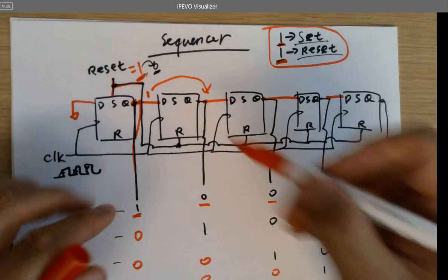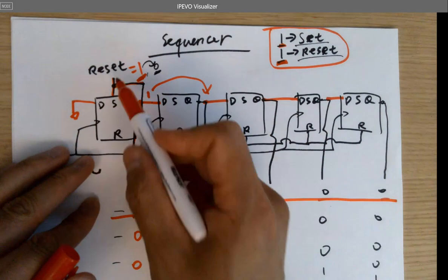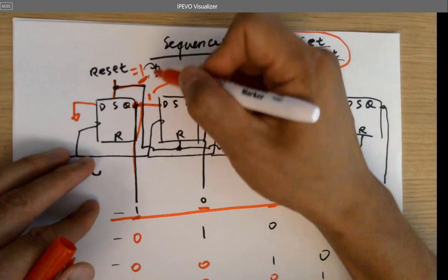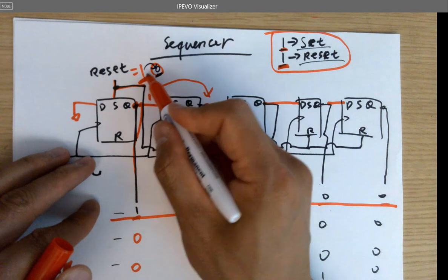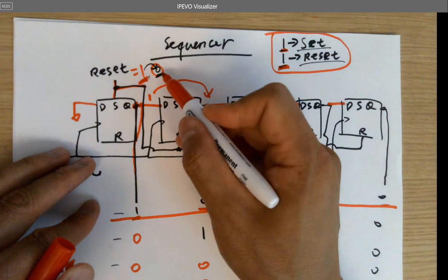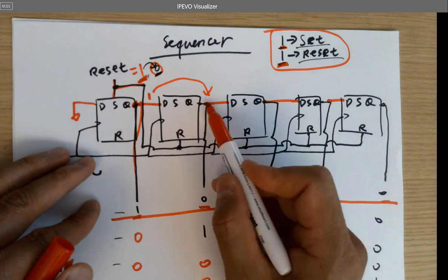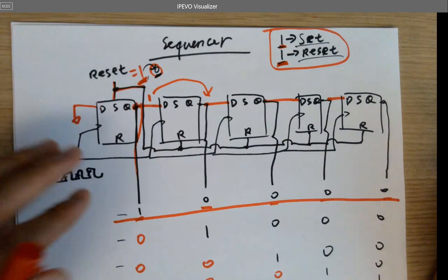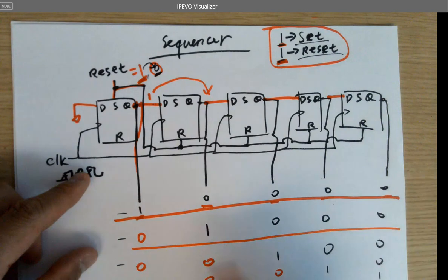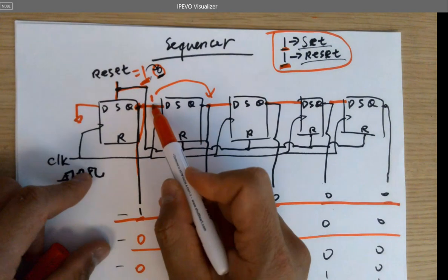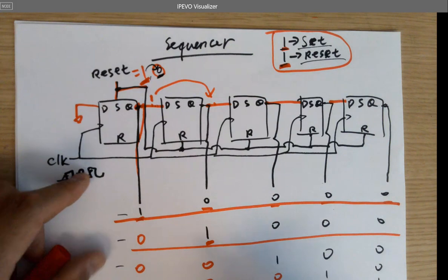And then they are changing because after the first cycle here, they're not being reset because I put a 0 right after that. So only the first cycle I put a 1 here to reset all the following ones, but after that I release them so they become D flip-flops. They are able to register D to Q. That allows, for example in the second cycle, this one to be registered here. That's why you are getting a 1 here. So they are being shifted.